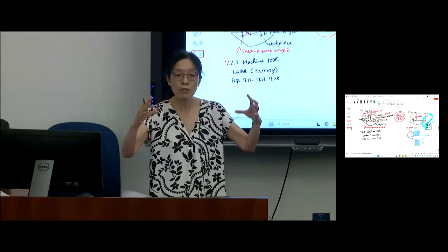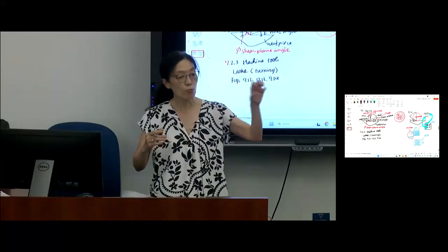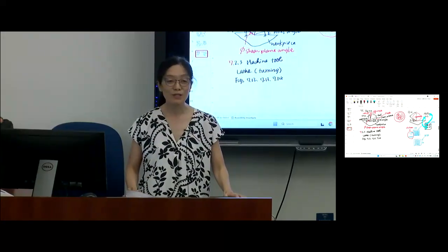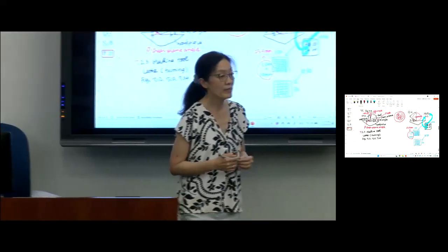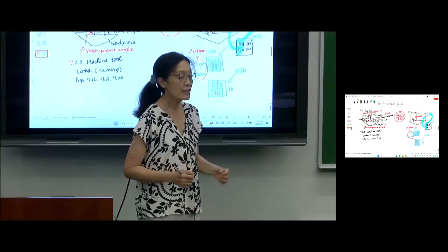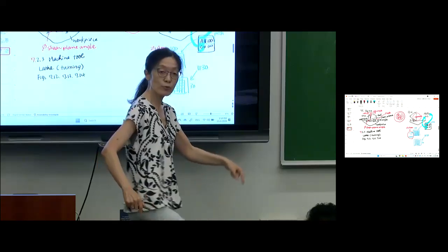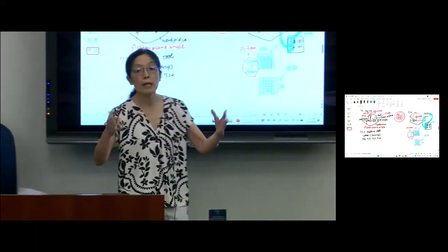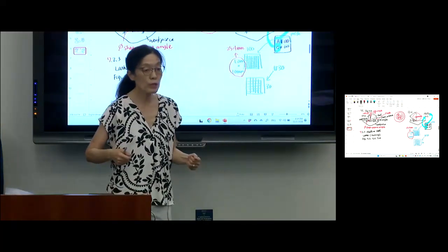How to stop the machine if you don't have any emergency stop button, or you don't use that kind of manual small one? You either pull it out of gear, step on the brake. Sometimes you have a brake underneath, so you have to foot the brake, right? And if you have an even smaller one, put it into neutral. That's how you stop the machine.